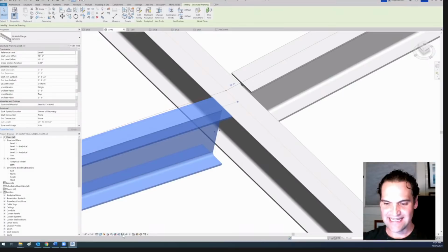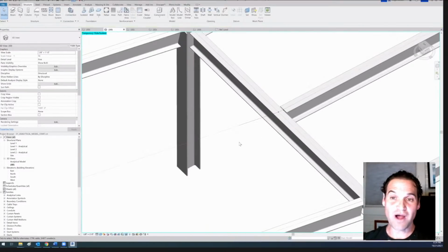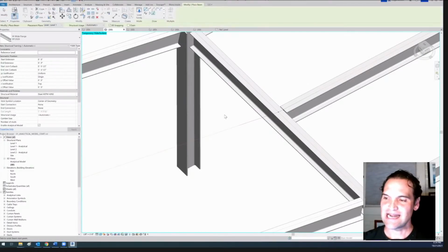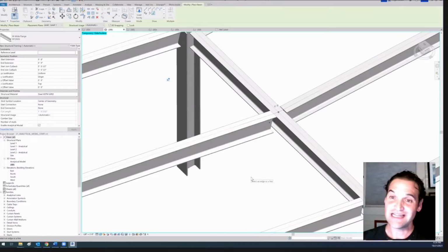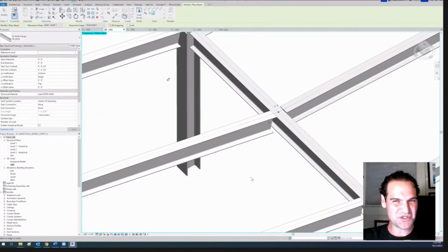So I actually hid the beam like this, and I get goosebumps every time I do this. I already have the line where I want because they have the smart points. Then I just took another beam and, in 3D snap, I snapped it down in that spot. And then I was like, whoa, wait a minute. What did I just do? Okay, now I'm using an analytical line, a smart 2-point line, 2 points to place a beam. But it still belongs to another beam.